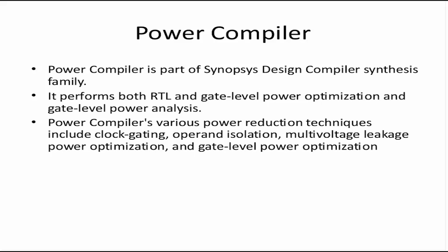RTL does not have gates, right? Verilog RTL, for example, has declarations of wires, but it does not actually have gates. And there is no concept of reporting power on RTL. You can analyze RTL to reduce power. You can employ some techniques in RTL itself to reduce power, but what the actual power number is, you cannot know, because power numbers are gate and technology dependent.